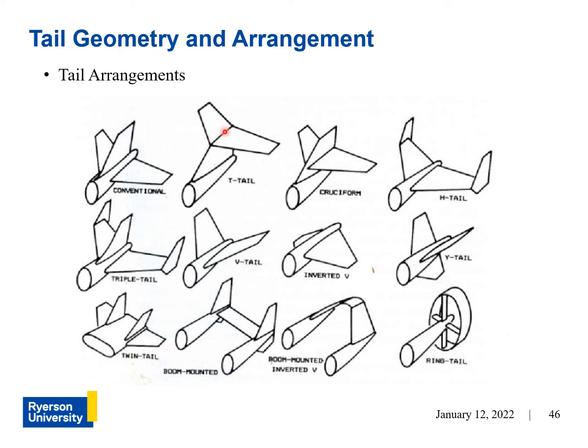But it allows for a smaller vertical tail and keeps the horizontal tail surface away from the wake of the wing. So because the horizontal tail surface is higher here compared to here, the wing, which is usually located along this line here, the airflow that comes from the wing is usually disturbed. So by moving the horizontal tail surface higher, the airflow that is seen by this surface is much cleaner than it would be for, let's say, this configuration here.